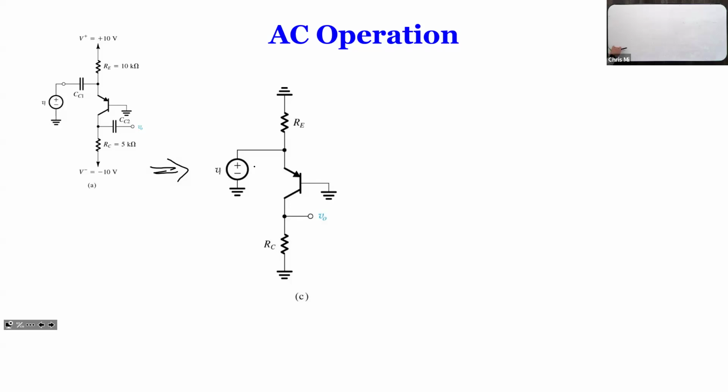So now actually you have two grounds. One at the emitter, which is minus 10 volts, which becomes ground. And another one is that VCC, 10 volts, also becomes a ground. So this is our small signal model. So when you look at this, you know that this is a small signal model. This is not actually how a BJT would work in real life.